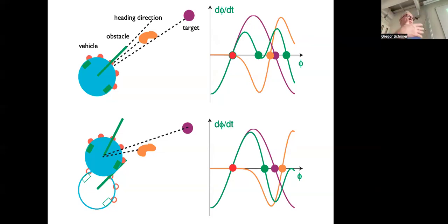That depends on what kind of sensor you do. Sometimes physically, the sensors need some integration time. Like we had these light dependent resistors, forgot the exact term, and they take some integration time to stabilize infrared light, or you can have just some estimation, stabilization of the estimation value of some time, and that gives you some minimum time you need between computational steps, and that means your computational steps have to be much smaller than the relaxation time, and so you can see that you cannot make these relaxation times arbitrarily small.